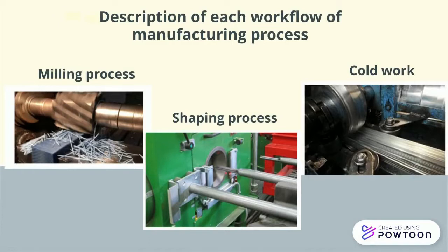Cold work. Cold drawing is a metal shaping method in which a piece of metal is driven through a single or sequence of dies, lowering the original part's cross-section size. Cold drawing produces a dimensionally uniform end product while increasing yield and tensile strength. As a result, the stiffness of the tubing steel increases.